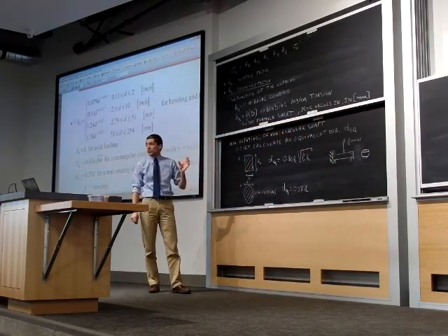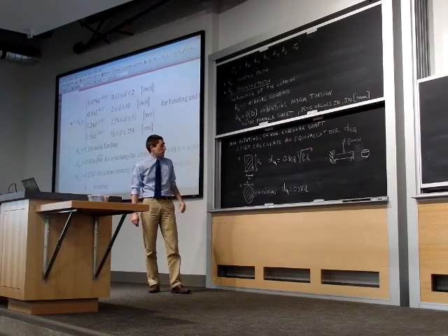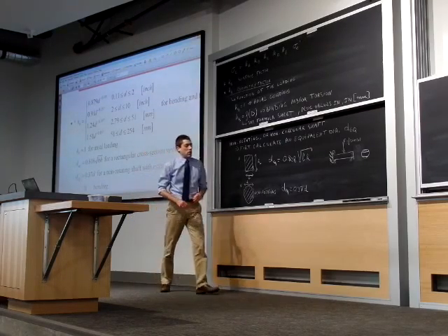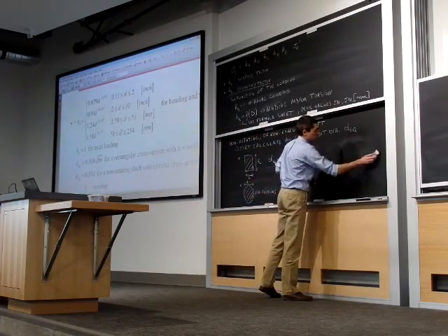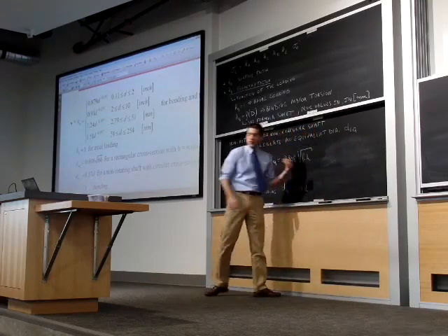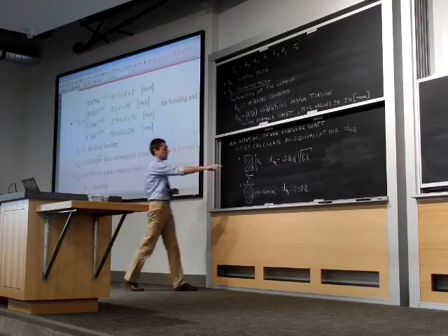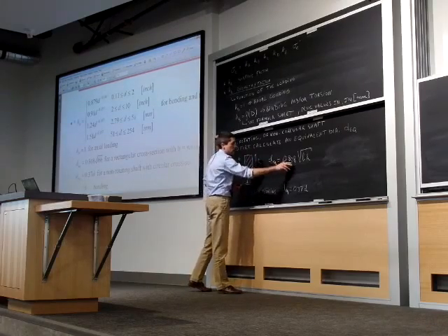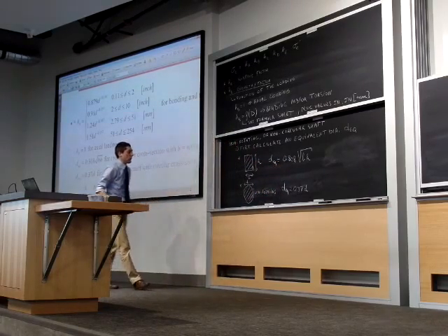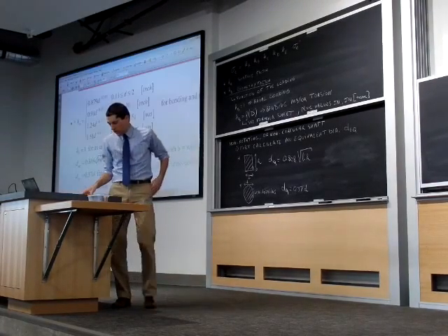So you see that the stress distribution in the shaft is different for different loading conditions, rotating versus non-rotating. And as such, we need to account for that in our calculation of the fatigue failure. And so this is to build your intuition. And you should do the reading, in the book it explains nicely. It's not very difficult how you derive these equivalent diameters, but it's interesting to see how it's done. Okay, that's KB. Let's talk about KC.